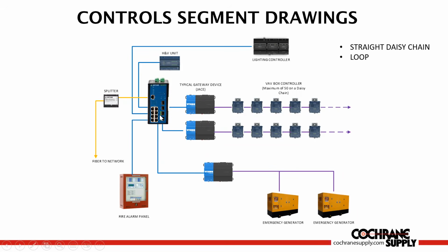So you will have 2 spare ports for future integration or to add equipment, anything that you like to do with those ports, or they just may be spare ports, right? When the contractor is off the job, systems integrator is off the job, you lock those ports through the software. Me personally, I would add port locks also.